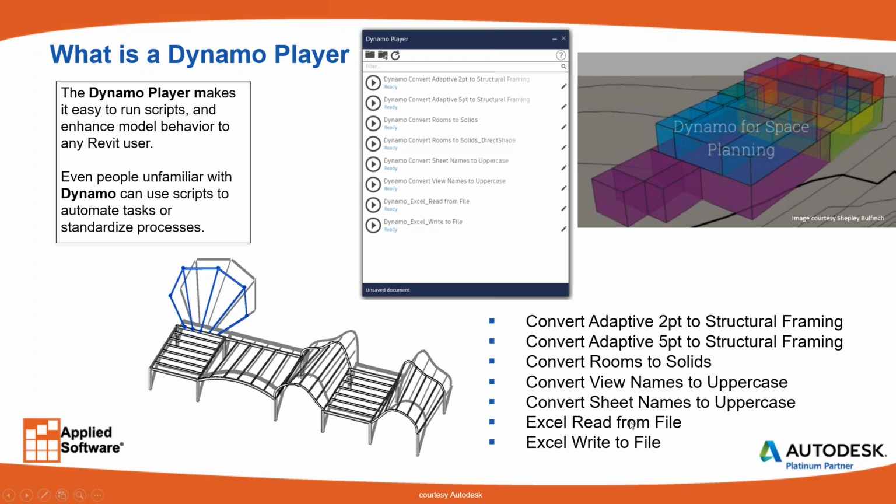I'll just go over these. These are a few of the graphs I created earlier. Taking data from Excel into Revit and back from Revit to Excel would be one of the functions of Dynamo. Converting sheet names and view names to uppercase, for example, is a very well-known thing that nobody remembers until the end of the project. If you have 200 sheets, it would be very difficult to change them to uppercase, renaming every single one of them. Dynamo can do that in one click.